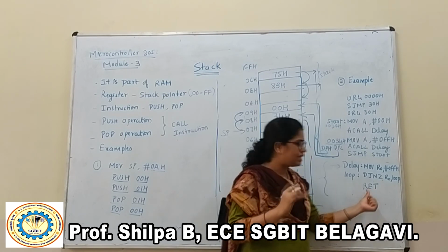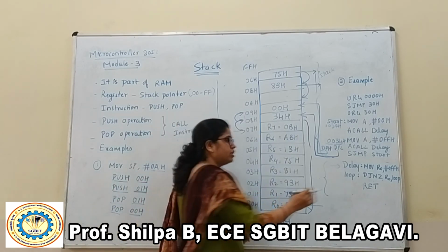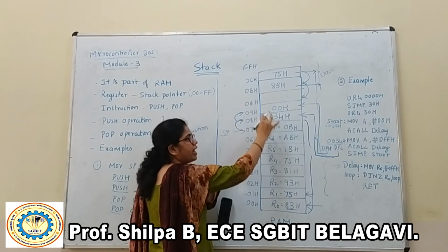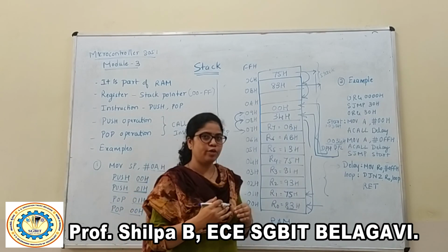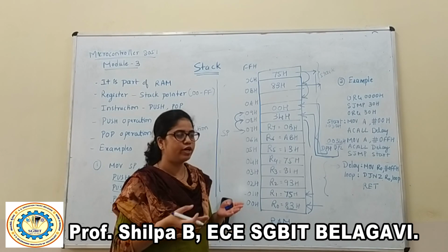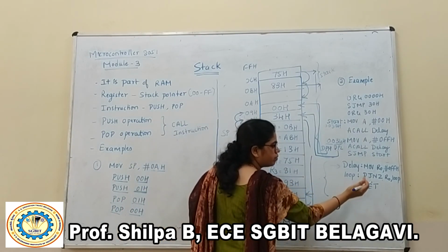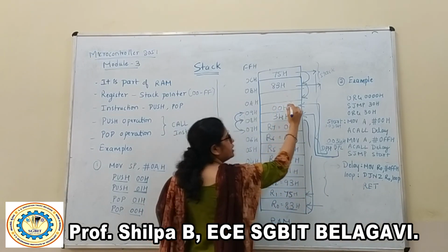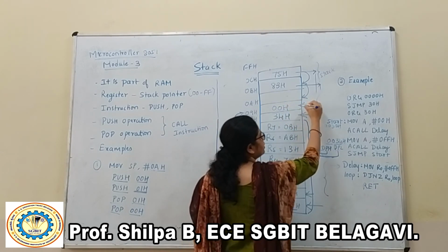What the return instruction does is, whenever return comes, it goes to the stack and gets back the address, because you should know, from the subroutine program, when I am diverting back to the main program, where to go? For that reason, whenever return is read by the 8051, it goes back to the stack and retrieves this data. What is this data? That is 00, that is DPH.